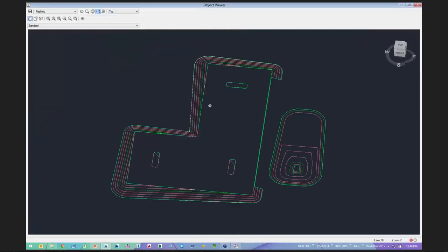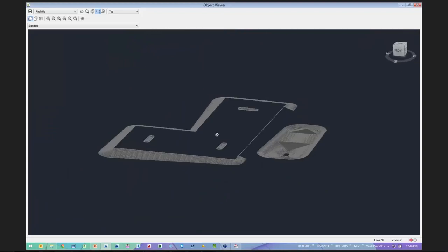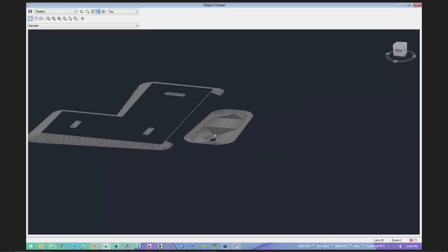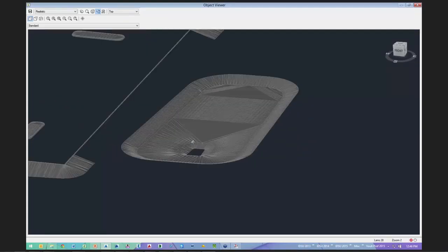So, but is this what we want? Not necessarily. Again, it's not triangulating from this lower piece, this lower feature line all the way up to there. And we're saying we want a constant grade from right there all the way up to there. What we're getting instead is it's triangulating straight across here. So this whole area is just flat right up here. We don't want that. We want it sheet draining all the way down here.